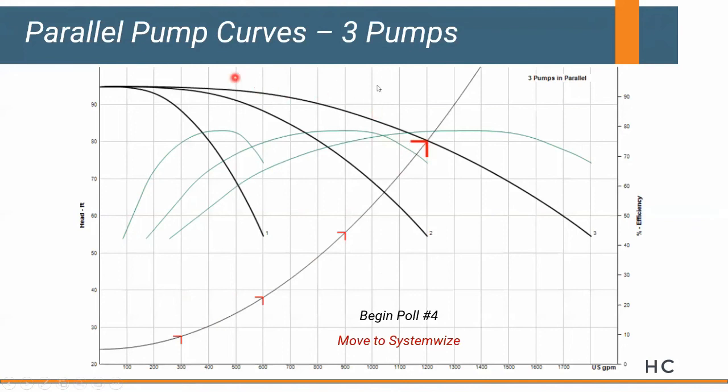It's going to move left, and design day or worst case is going to be full output at 1,200 gallons a minute. So there's a lot of variables as it relates to parallel pumping, system curves, and how to stage pumps. It's not a red flag, but certainly warrants additional consideration if we're looking to run a single pump in a large system.